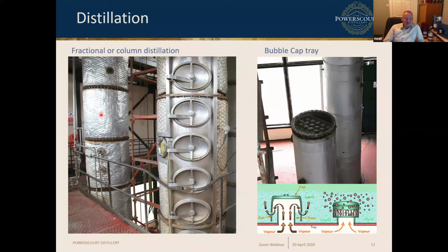In that section near the bottom, you'll see two little parts where that's the feed going into the column. So you can actually put your alcohol in, and this is about just a bit more than halfway up the column. The alcohol will distill up in strength as it goes up through the column, but the water will go down and out the bottom. And you can also draw off different alcohol concentrations, and in those you will get what we call the fusel oils and the heads.